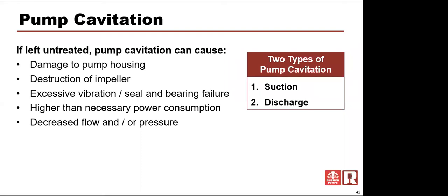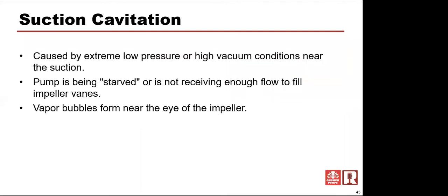And it certainly would have some effect on power consumption. More noticeably, it's going to have an effect on the amount of flow rate and some pressure decrease, because those vapor bubbles are taking up what should be taken up. The volume that should be taken up by water is now being taken up by the vapor bubbles as it goes through this pump. So it affects performance as well, besides damaging the pump and seal.